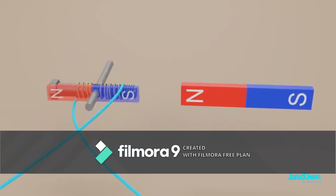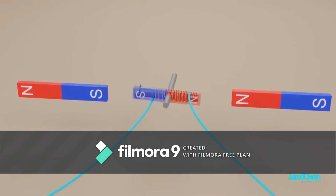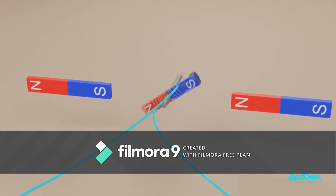To make this stronger, let's bring in another permanent magnet on the side. Notice how this side has the south pole towards the center, and this side has the north pole towards the center. The side magnets work together to spin the one in the middle. This right here shows the very basics of an electric motor. But we need to make a few improvements.